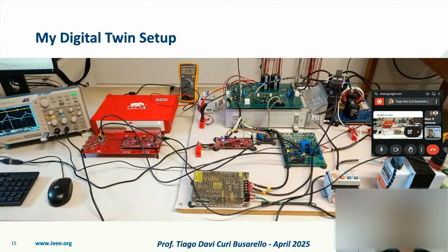And here I have my real-time simulator running the model. You can see that I have identical microcontrollers. Again, it is much easier to synchronize the carriers of these microcontrollers because they have registers that can be transmitted to this one. And this value of the registers can be set as 0 for this PWM. In the end, we're going to have synchronized PWMs.